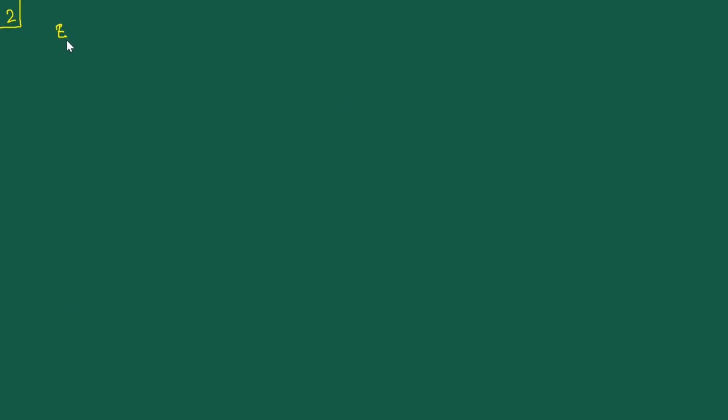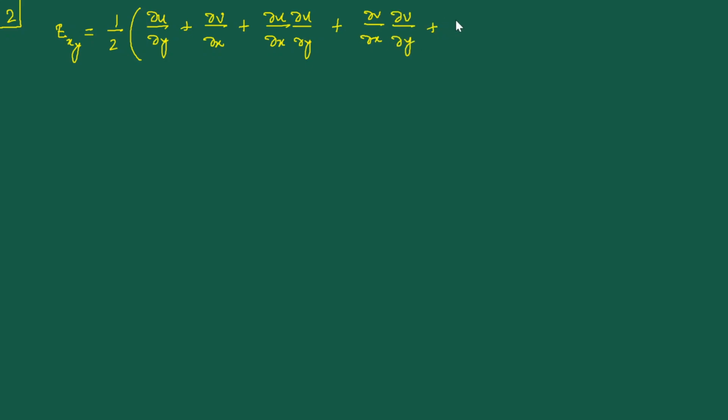Next, we have for EXY, the general expression is ∂U/∂Y plus ∂V/∂X plus ∂U/∂X ∂U/∂Y. So these are the quadratic terms for this shear strain, ∂V/∂X ∂V/∂Y plus ∂W/∂X ∂W/∂Y. All right, so we have to do this a little bit more carefully.